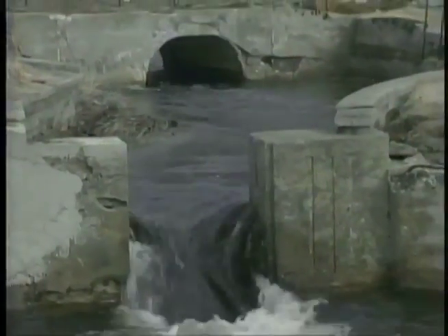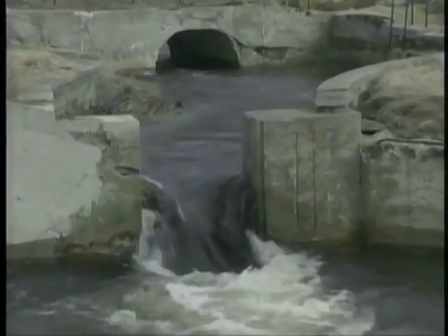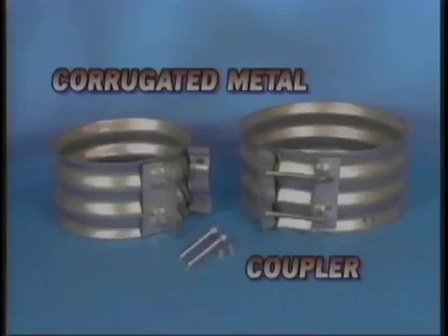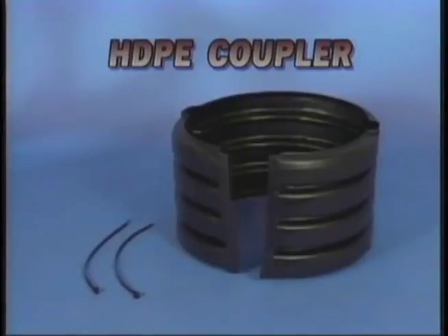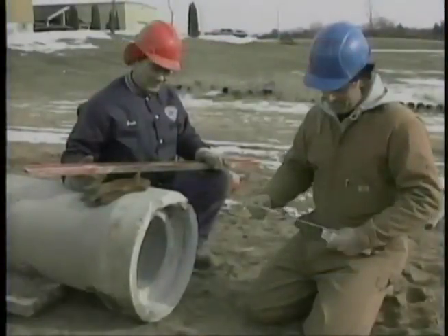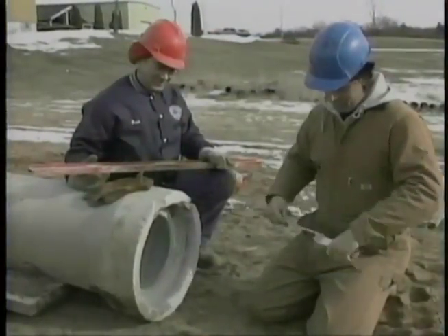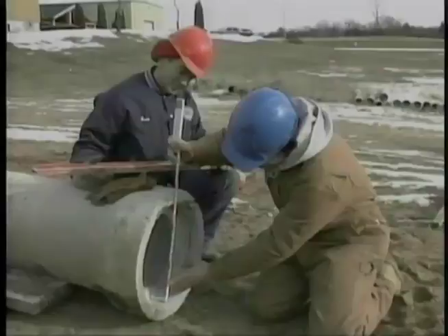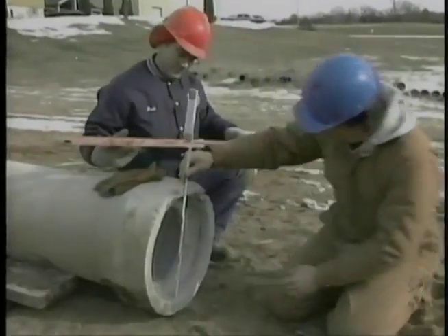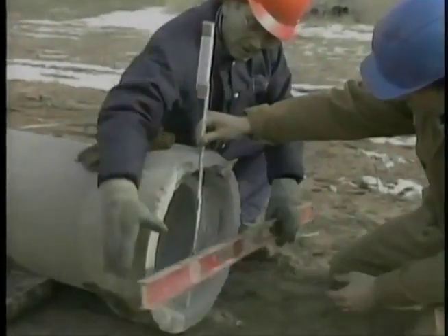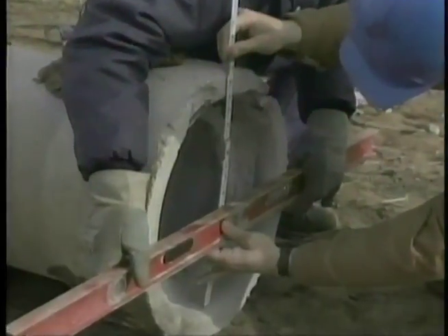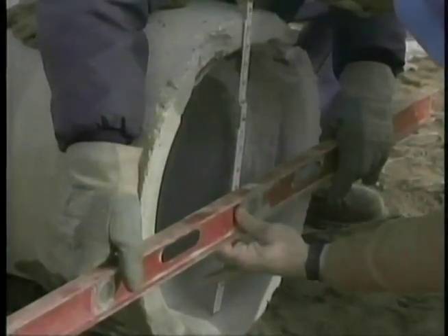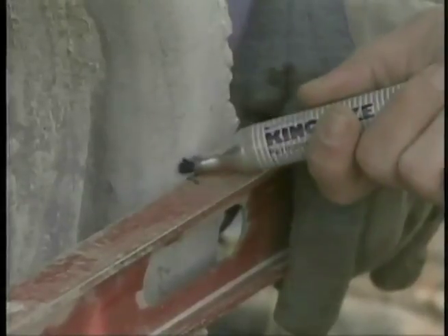After a number of years, a storm drain pipe may need replacement or repair due to failure from ground pressure or root systems. Repairs to storm sewers are made with the same type of couplers that were required in the initial installation. When repairing concrete pipe, the damaged joint of pipe must be completely removed and replaced with an entirely new joint. Measure the diameter of the bell on the replacement pipe and divide in half. Mark the bell at the midpoint for the saw cut.